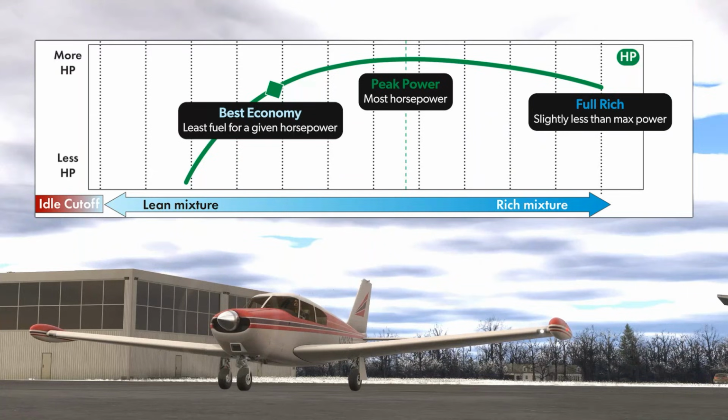It's not that any cylinders are misfiring. It's not that cylinders are too lean for proper combustion. Actually, the reason has to do with having multiple cylinders. So right now, the diamond on the chart is depicting a single cylinder. In reality, this Comanche that's in the picture and that we'll be using for examples here has 6 cylinders. And those cylinders get different amounts of fuel. And so they fall at slightly different points on this curve.